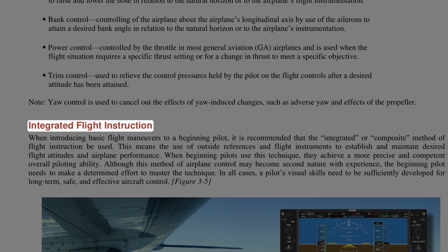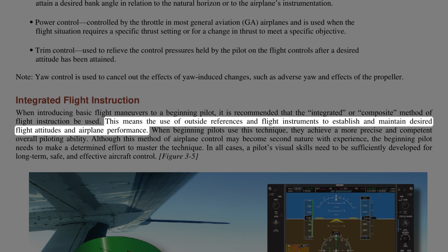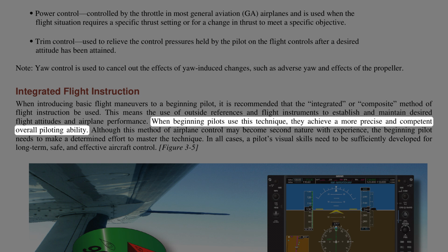Integrated flight instruction. When introducing basic flight maneuvers to a beginning pilot, it is recommended that the integrated, or composite, method of flight instruction be used. This means the use of outside references and flight instruments to establish and maintain desired flight attitudes and airplane performance. When beginning pilots use this technique, they achieve a more precise and competent overall piloting ability.